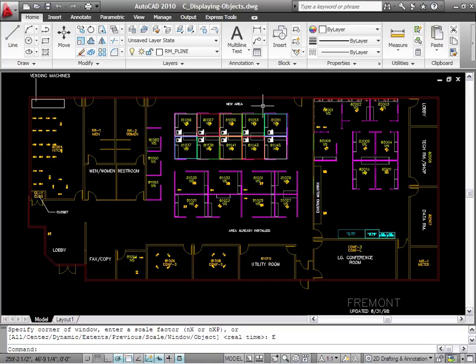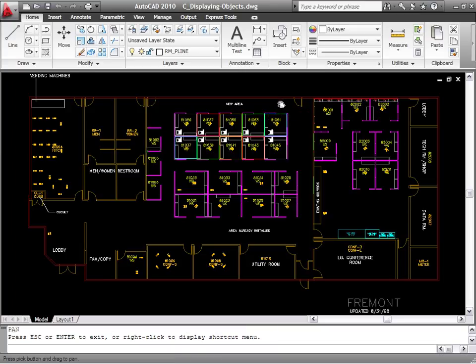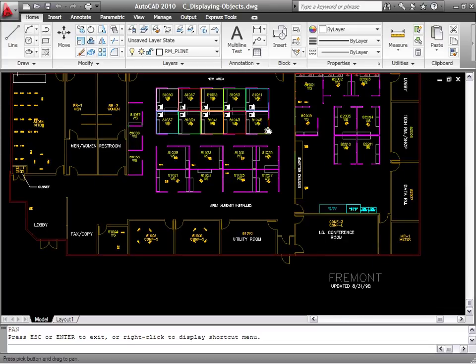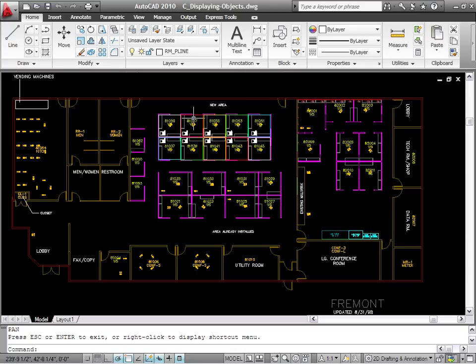So probably you have a problem with your roller mouse, that you want to pan around, you have difficulty. Another option to pan around the drawing is by hitting the command pan. The command would be the first letter of the word, which is P for pan. To enter the command, spacebar. When you hit spacebar, you can immediately see the cursor becomes a hand, and you can pan the drawing again. When you finish the command, escape. When you hit the escape button, the cursor goes back to normal.